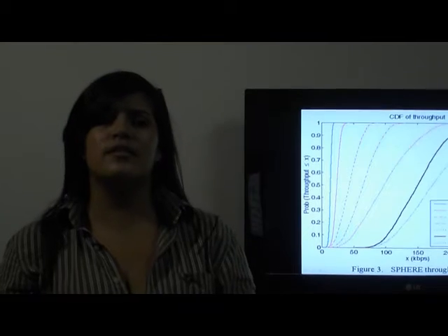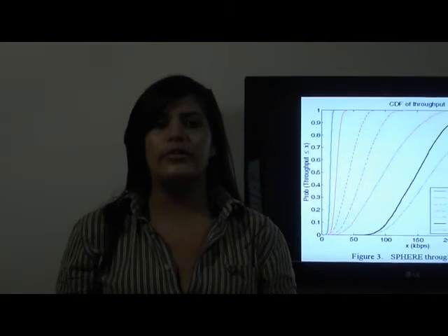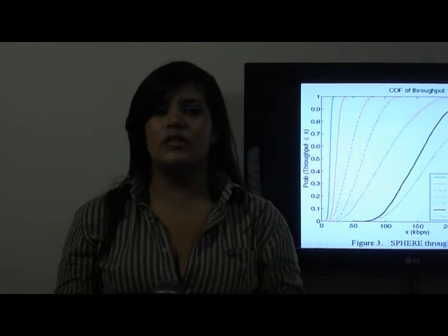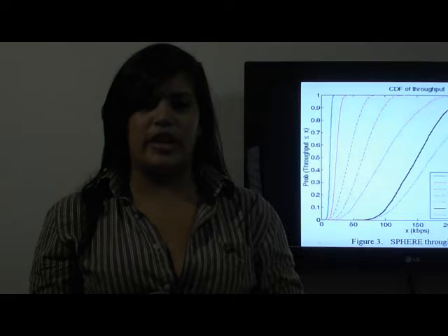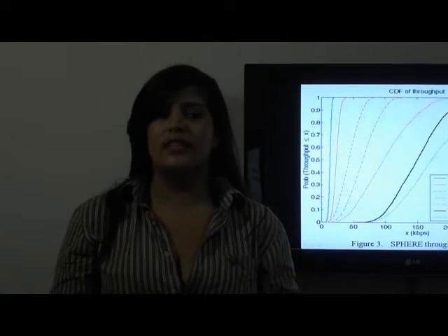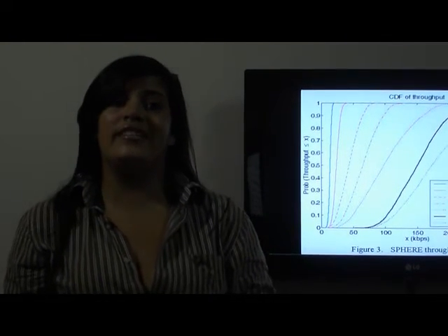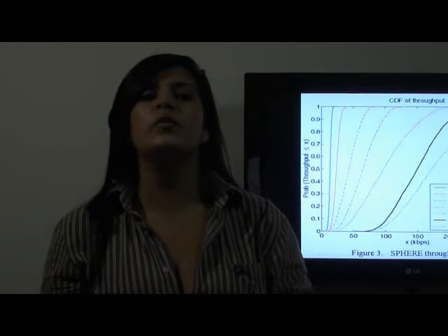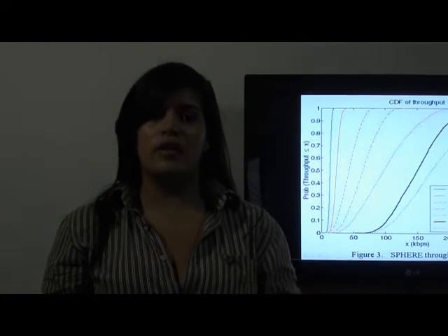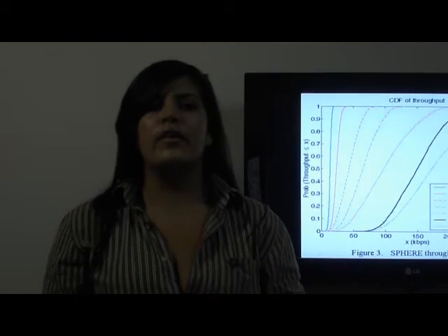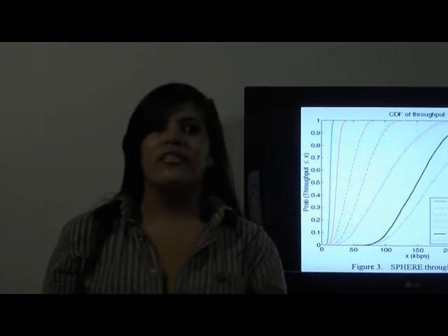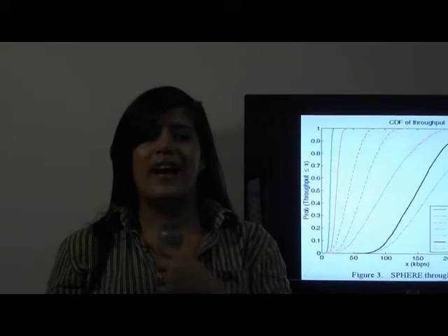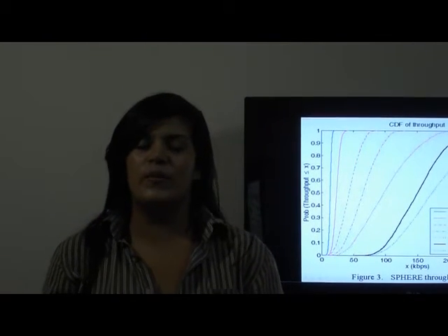In fact, the performance is lower than the maximum theoretical values given the low cell radius, high transmitting power and high cell load used to conduct this simulation. These conditions increase the interference levels, which in turn increase the experienced BLER, decrease the throughput performance and promote adaptive radio interface changes, as modeled in Sphere, to user transmission modes with higher protection and lower bitrate.